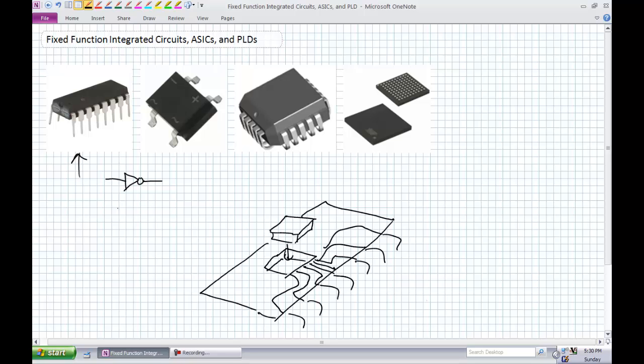This one on the left, that's what's known as a dual inline package. Dual because there are two rows. Okay, they are aligned so that they will fit inside your protoboard, and additionally they are called through hole, in contrast to surface mount. Okay, which types of the technology do you think goes through holes? The through hole. Which type of technology do you think goes on top of a board? Surface mount. Okay, SMT, surface mount technology.